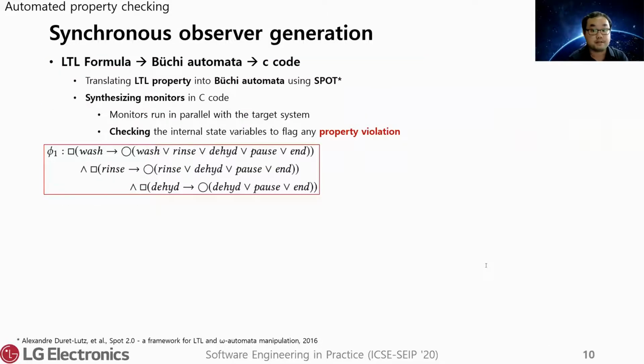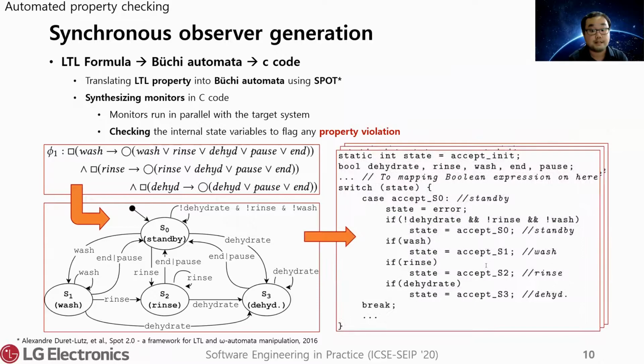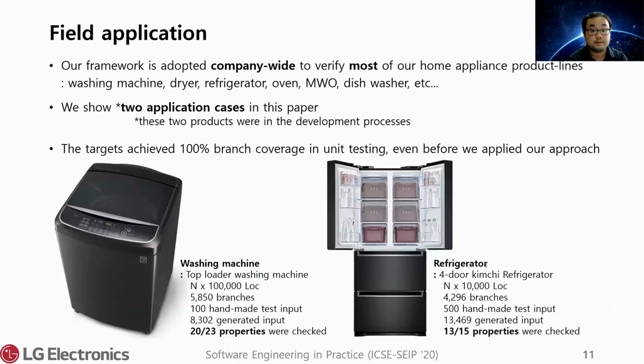Once the properties are formalized to LTL, we can easily translate them into Büchi automata and then synthesize monitors in C code. The monitors run in parallel with the target system and check the state variables in target system to flag any property violation. So that was for the tool. A fast simulation, large amount of test inputs, and strong oracles.